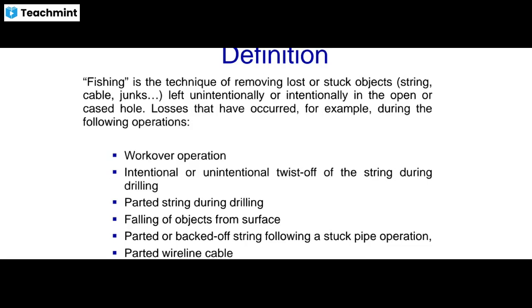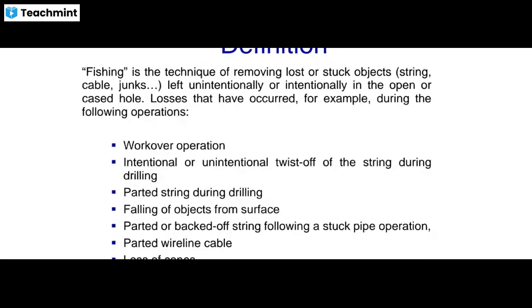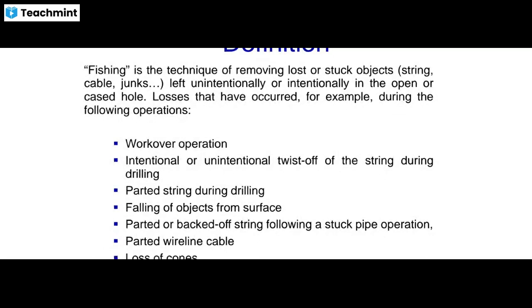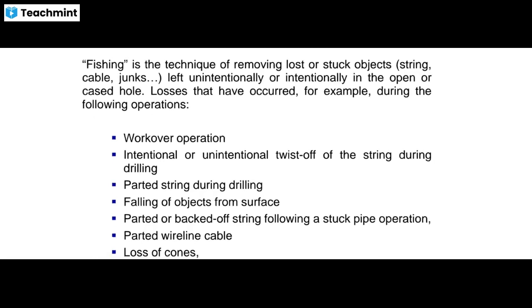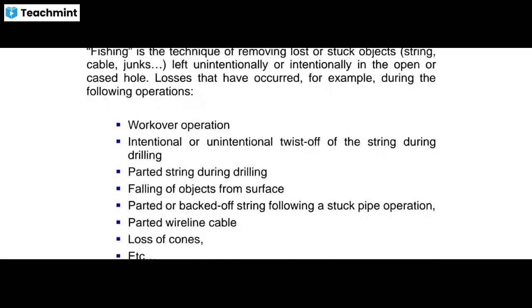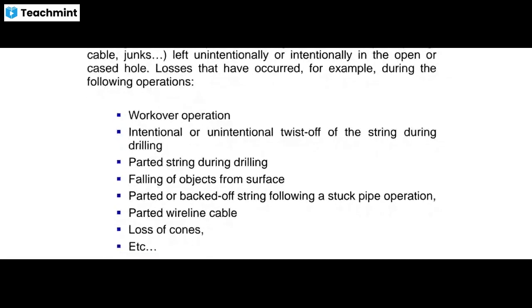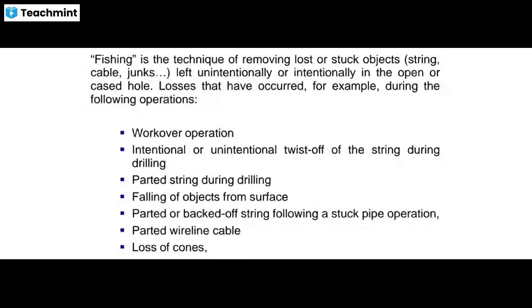For example, workover operations, intentional or unintentional twist-off of the string during drilling, parted string during drilling, falling of objects from the surface, parted or backed-off string following a stuck pipe operation, and then parted wireline cables and loss of cones from the bits, etc. So these are the points which you should know.